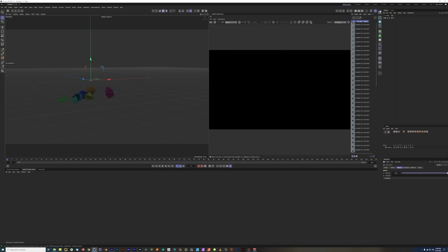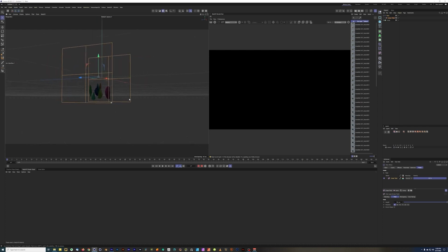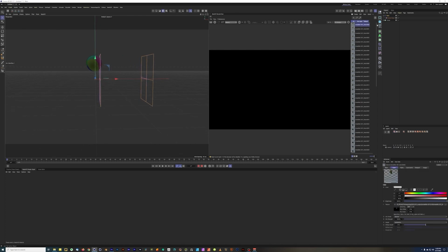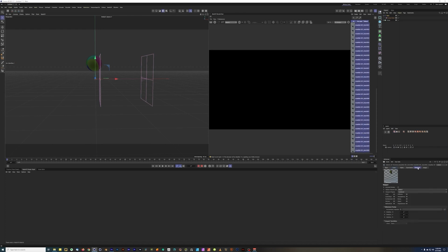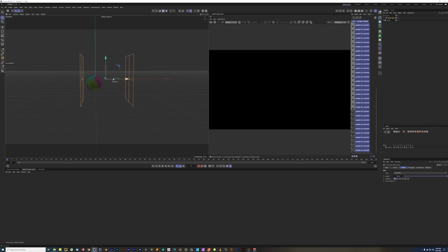But what that also means, if I turn that all the way up, is if we use a field, like a linear field here, we can control that forward and backward. Now remember, it's 2D. So you're just controlling the animation playing on this card. Another thing that I like to do if I'm doing viewport stuff is just to select all these, and on the viewport tab, turn it to no scaling, get a little bit better quality. So you can use this in a variety of ways.